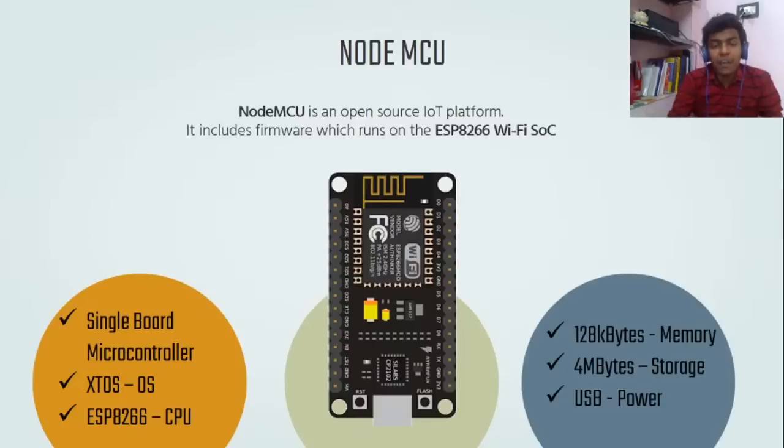But if you interface the ESP8266 module externally, we need to write a lot of AT command programs to configure the ESP8266. If you use this kind of board, a lot of libraries are already present, so you can easily program it and develop that kind of application. It is very easy to use NodeMCU compared to Arduino. That is the reason why we are using NodeMCU.